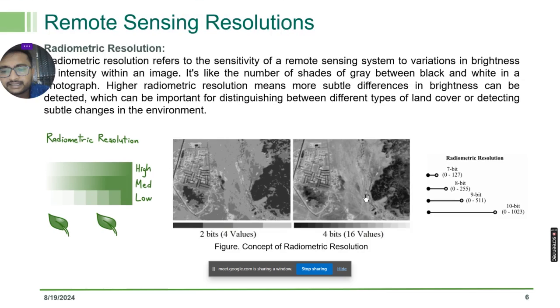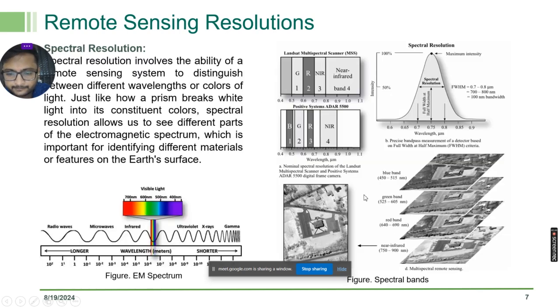So like that we will see the different sensitivity of different objects, and then we will present it in terms of bits. When we talk about the satellite data we are acquiring, the Landsat satellite, if you have heard of it, has 16-bit radiometric resolution. Some satellites also have 24-bit resolution. We will see those things with real life data sets afterward.